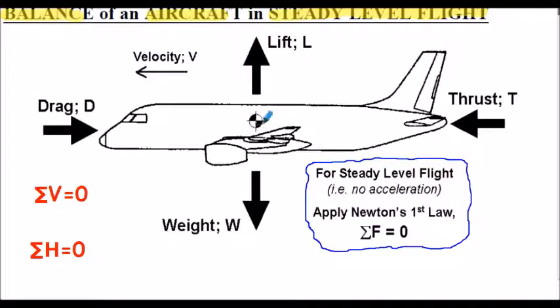If you look at the forces acting on the body, and we consider the horizontal forces here, then the thrust from the engines, labelled T here, pushing the aircraft forward, is balanced by the drag force around the aircraft due to the aerodynamic friction effects and so on. So that's what's called a horizontal balance. If I add up all the horizontal forces, in this case I get the thrust minus the drag is equal to 0. That's the expression for the horizontal balance. And I'm assuming in this case that the positive direction is in this sense.